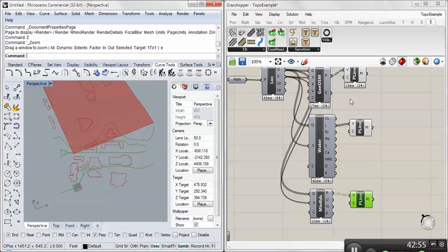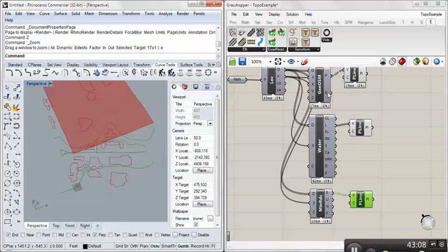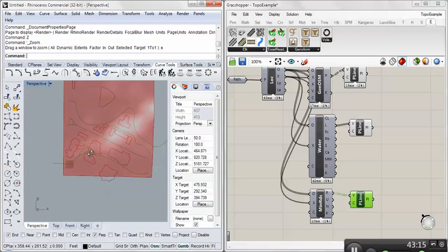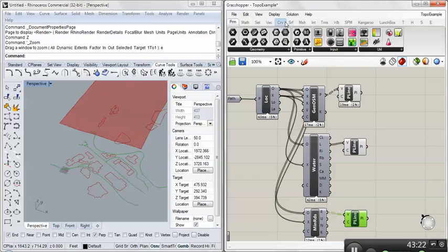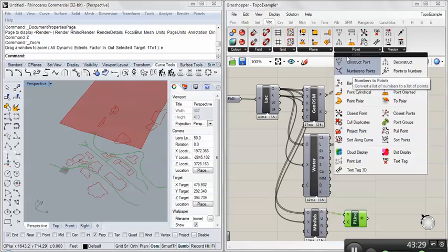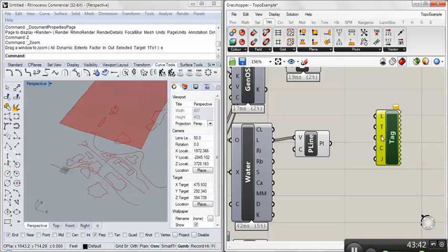Okay, the other thing that comes out of the roads and the generic is the labels, if there are any. So this is Crescent Road, Jayhawk Boulevard, Memorial Drive. Here we get the building names. In order to show these labels, you can show them also on the model. So we want to go to Vector, Point, and under Point are a couple items for letting you show textual information. Let's see, I think 3D text tag will do, that'll work. This is the one with more options.